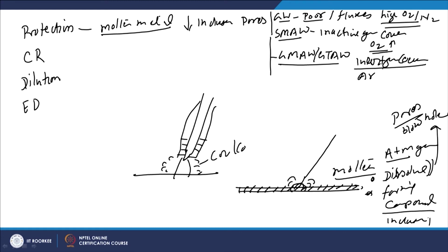For this purpose, we may use argon or helium, or a mixture of argon plus carbon dioxide, or even CO2 in the case of steel. If ferrous metals are to be deposited, then even CO2 can work to provide the required protection. For plasma also, an inert gas mixture is invariably used.